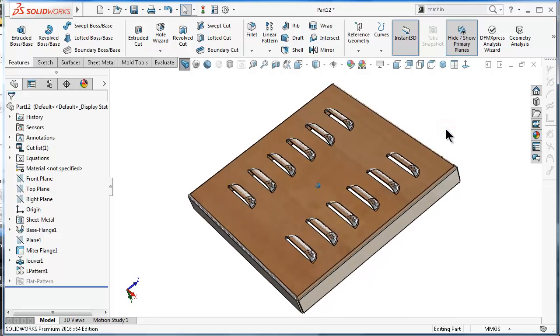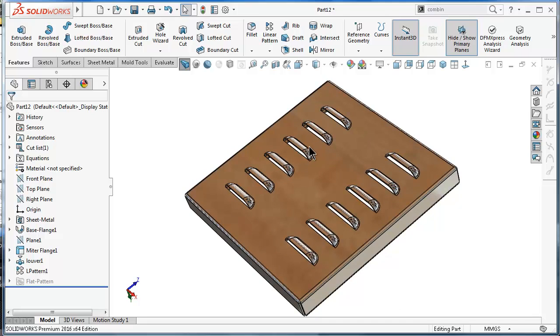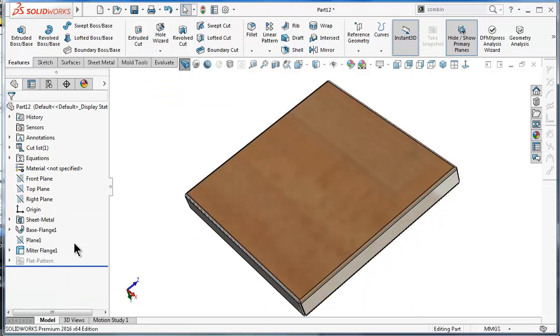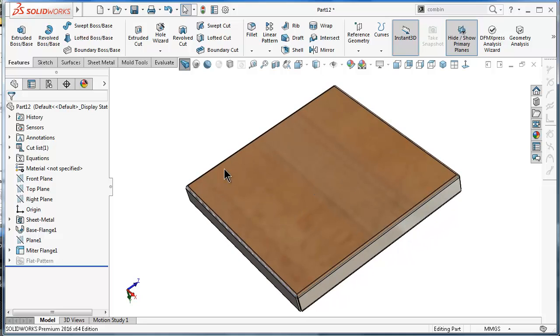This is first, and second, I would like to change the style of this grill by using the forming tools. I would like to have the louvers longer and create just one press die to create the whole louvers at once. So make it longer. That will increase the passing air volume, and making all in one press will also save production time. So delete the louvers and let's see how to create a custom forming tool.